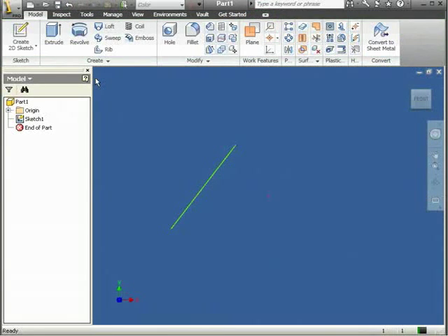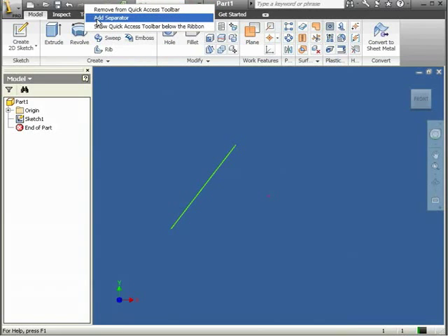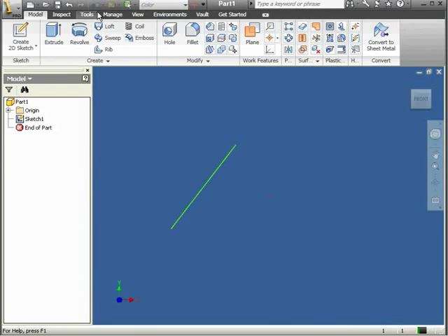Let's right-click on the Quick Access toolbar now. I want to check out some of the contextual menu options. From here, we can easily remove a command from the toolbar, add a separator, or show the Quick Access toolbar underneath the ribbon instead of on top. Here's my separator pipe. To remove that separator, right-click again and select Remove from the Quick Access toolbar.